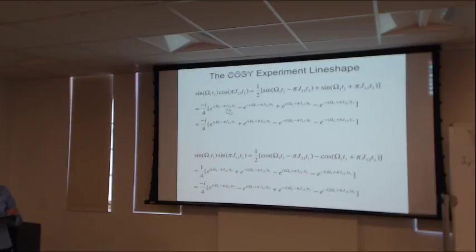We can go on then and write this in terms of complex exponentials using Euler's relation, and we see that we end up with 4 terms, two from this, 2 from that. In terms of Euler's relation, we have a positive frequency downshifted and negative frequencies, positive frequencies, negative frequencies.